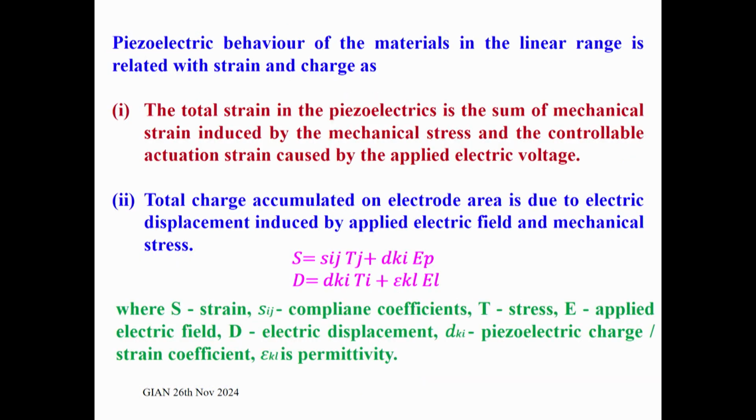Now, as far as the development of the materials is concerned, the piezoelectric behavior of the material in the linear range is related to the strain and charge. The total strain in the piezoelectric material is the sum of the mechanical strain induced by the mechanical stress and the controllable accumulation strain caused by the applied electric field. Both these reasons are responsible for the total strain in piezoelectric materials.